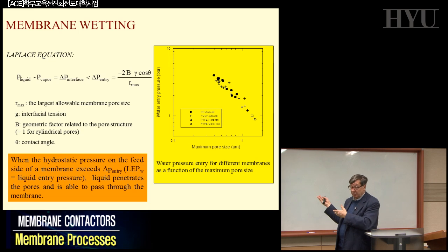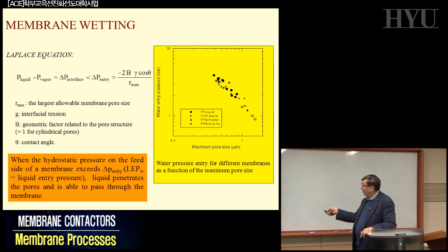That's why you use more energy. It's a little bit more tricky. Working at high temperature is always a problem, but you can solve it. And that's why people are working here on TIPS, because they want to produce membranes with a very narrow pore size distribution around this number to be utilized in this system and not having this problem down here. So that is one of the important aspects of the situation, to avoid as much as possible the big pores.